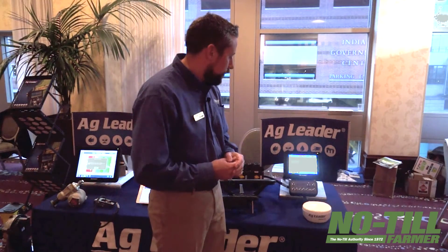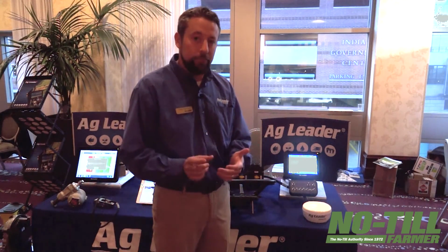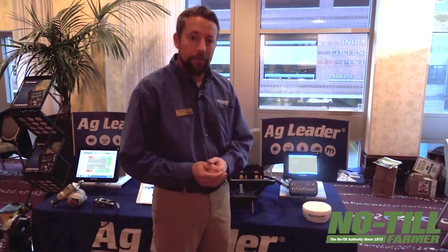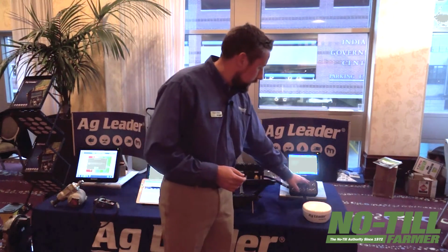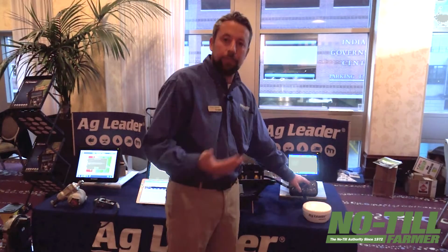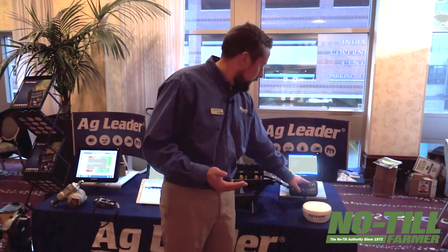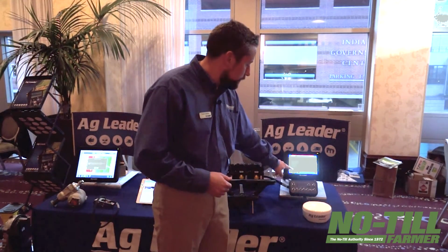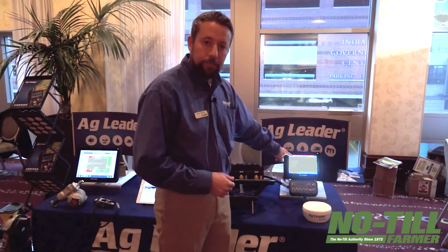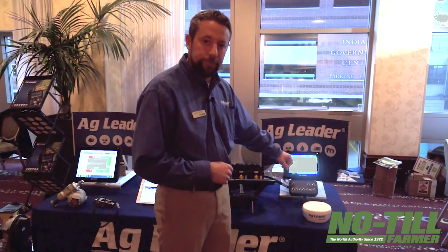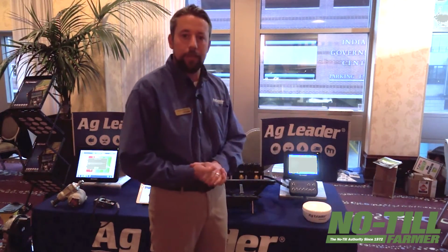We know that with the product he's spraying, the medium droplet size is the target he's going after. If he gets out of that range, say he speeds up his ground speed and all of a sudden our pressure jumps, it's going to alert him that he's too high on his pressure and help him do a better job at applicating that way.